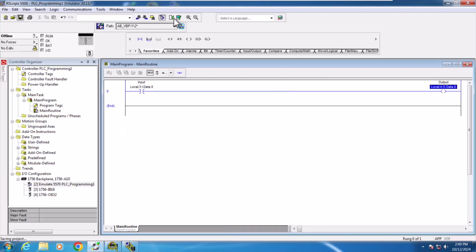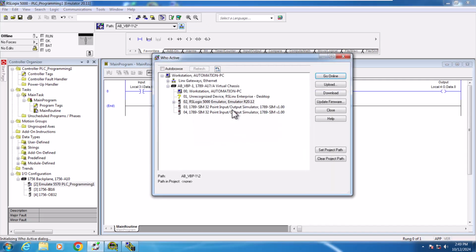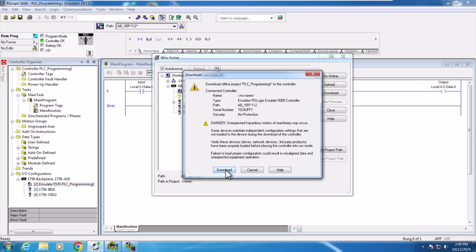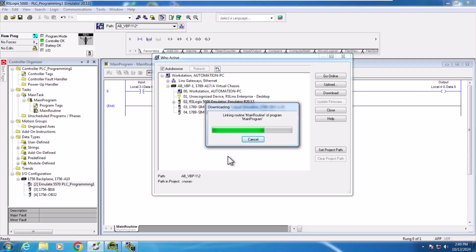I'm saving the program again with the updated I/O card settings. I'll verify it to ensure there are no errors in the configuration. Once the verification is successful, we'll go ahead and perform the download to transfer the program to the controller for real-time simulation. Before proceeding with the download, make sure you've carefully read and understood all the instructions. Ensuring that everything is properly configured will help avoid errors during the download process.